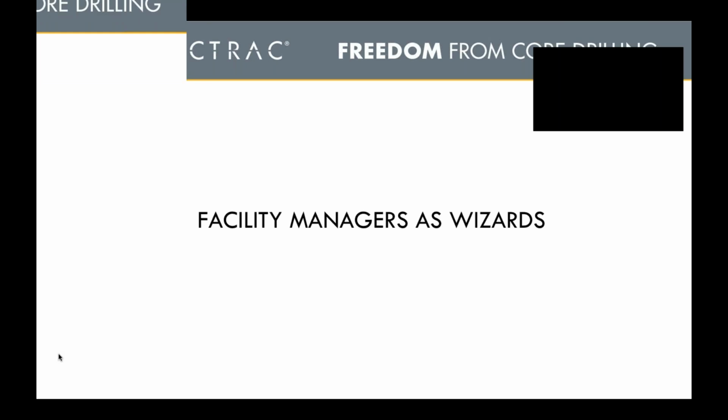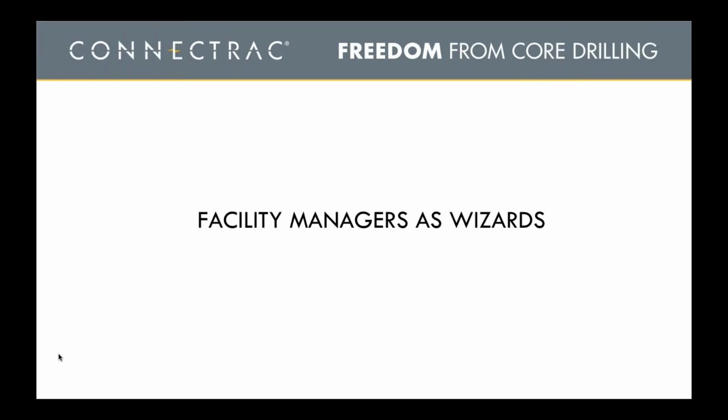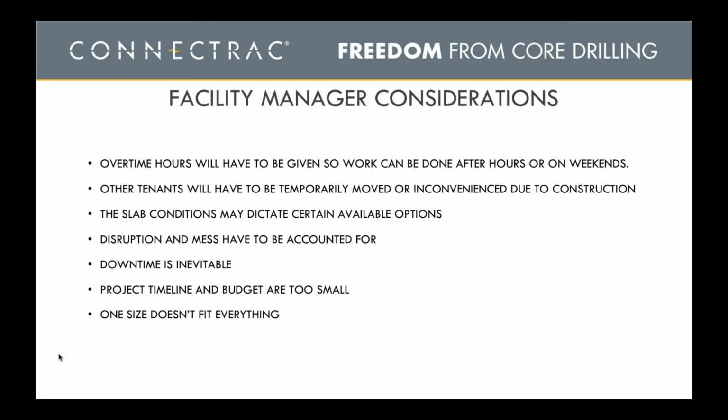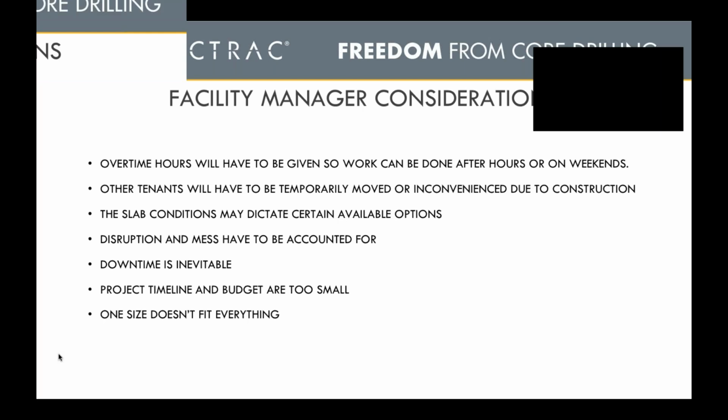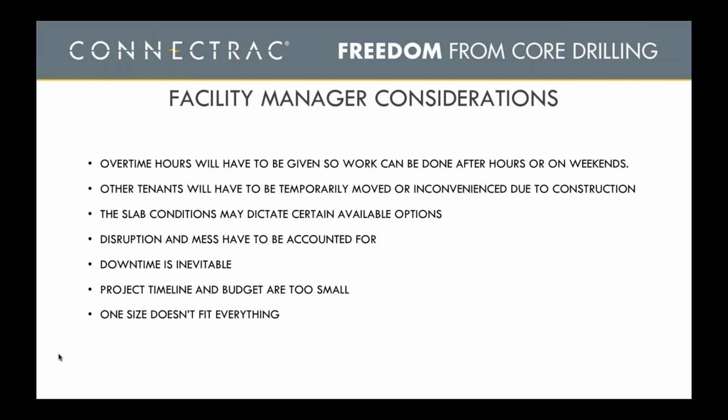The reality is, in order for you to make this happen, several other things have to occur. Here are some of the things, if you're going to normally bring in power into a space, that has to happen. Overtime hours have to be given, so you can work on overtime or on weekends. If you have other tenants in the facility, which you usually do, they have to be either moved or inconvenienced due to the construction. Even if somebody says, I want power right there, the slab conditions often dictate what are some available options. Another one that has to occur is disruption and mess always have to be accounted for.